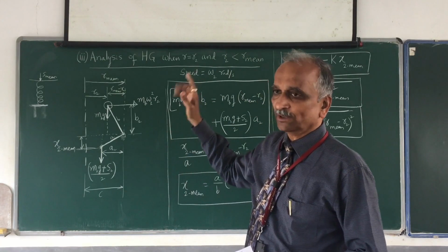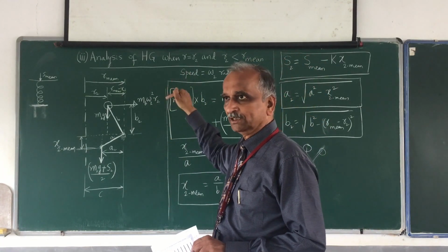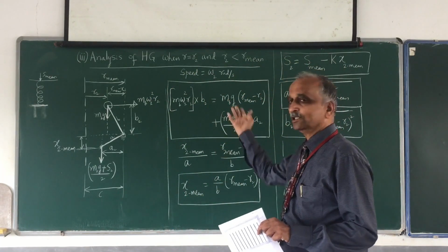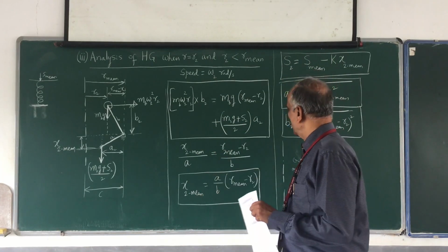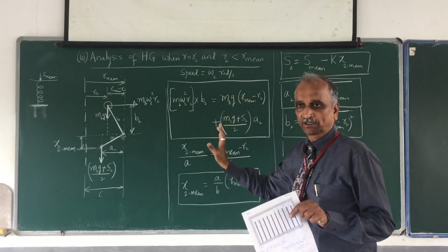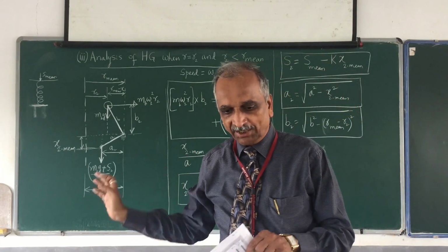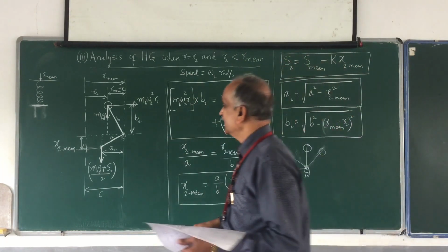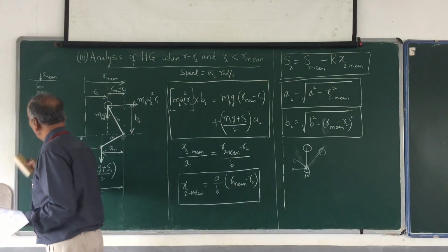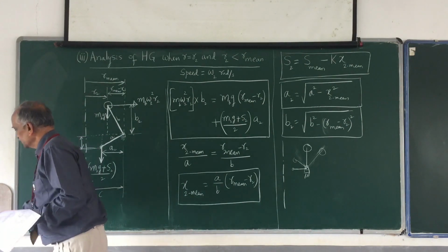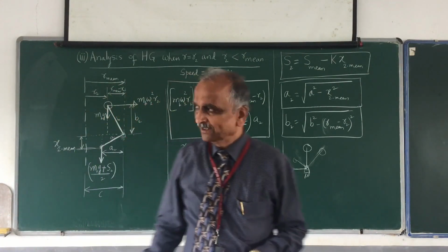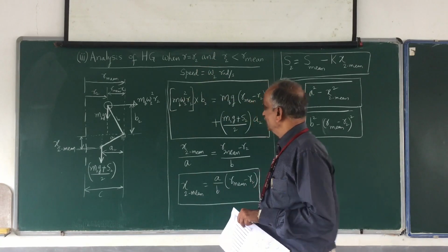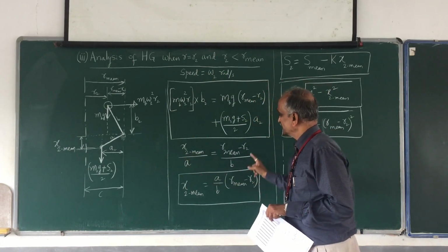Okay, I am referring to the mean position, where the ball arm is vertical, or in other words, the ball arm dimension B is parallel to the spindle axis. With respect to that, I would like to compare the other positions, and for that purpose I have used the mean position. There is nothing standard about it; I have used it for my analysis purpose. One more very important thing: whatever I have shown here is applicable for case 2 also. So here I find X2 and so on.